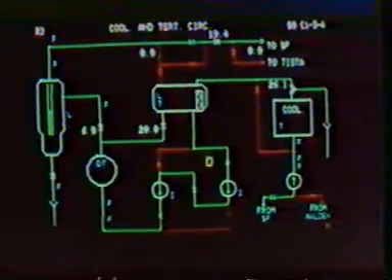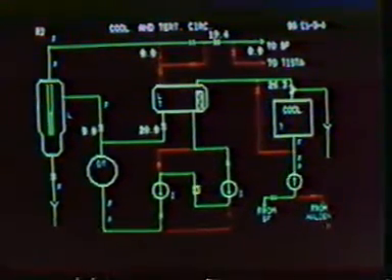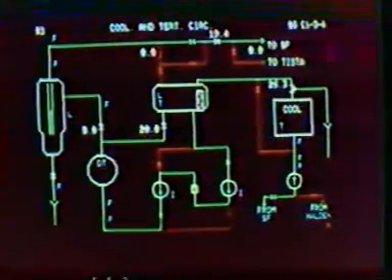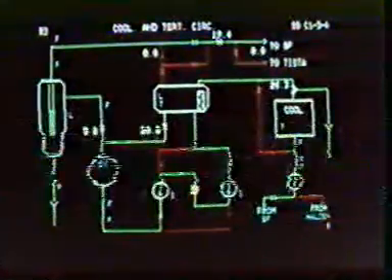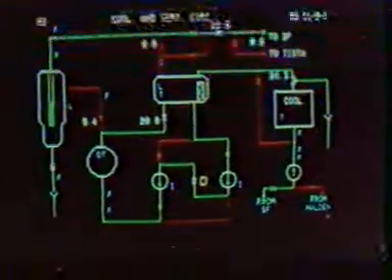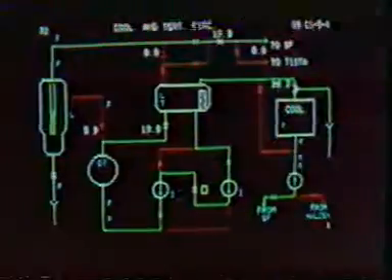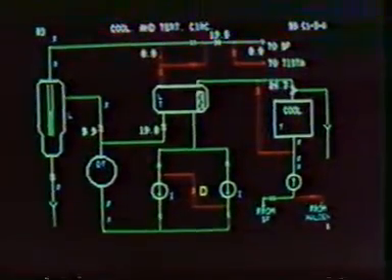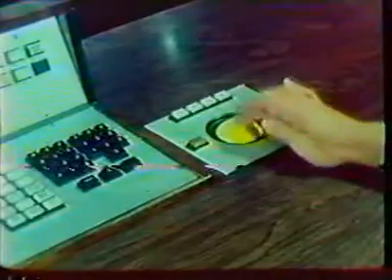To operate the control valves, the operator can address the proper valve directly by pushing buttons on the console. Notice how the mimic diagram follows changes in the process dynamically. For example, the valve symbol of the diagram and the lines it controls are changing color from red to green if the circuit is opened.